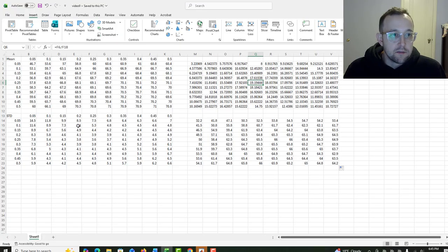Okay, I'm back. It's a different day. Not like the simulations actually took multiple days, but I just had to wait to make the rest of this video. So I defined a couple of metrics to help me pick out the best exciter location. Up here, I did the mean divided by the median. So I want high mean SPL and low standard deviation of SPL. And the highest number comes out being this point, which is F6 here. So that's 0.25, 0.25.